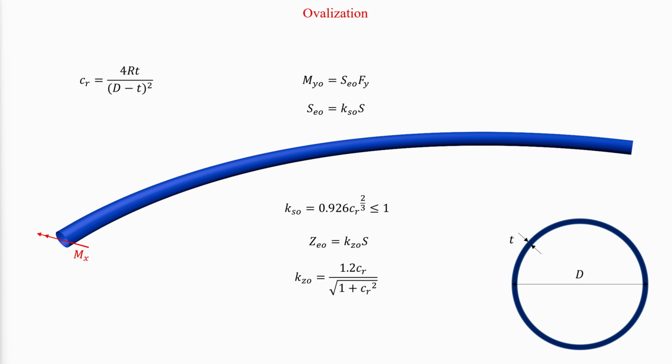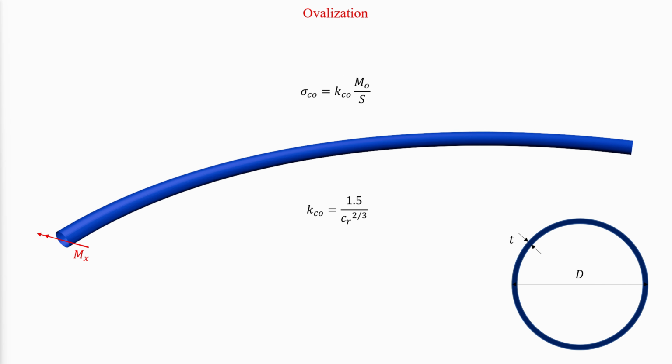For out-of-plane bending, the effective moment of inertia is identical to that of in-plane bending. When fatigue or local strength is an issue, the circumferential stresses can be calculated with a multiplier on the longitudinal flexural stress according to this equation.